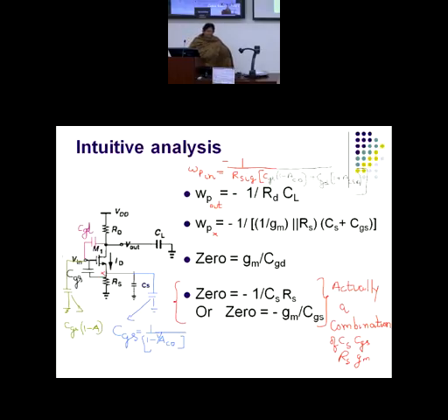Will you get a current through CS? You will not get it, because the source is grounded. The other node is also grounded. So that expression will not be valid. Please mind it. You will not get any impact. So something is written, that does not mean it must be correct. You should apply your reasoning also. Because for putting a 0, we know Vs has to go to 0. V source has to go to 0. Clear? So CS comes between ground and ground.